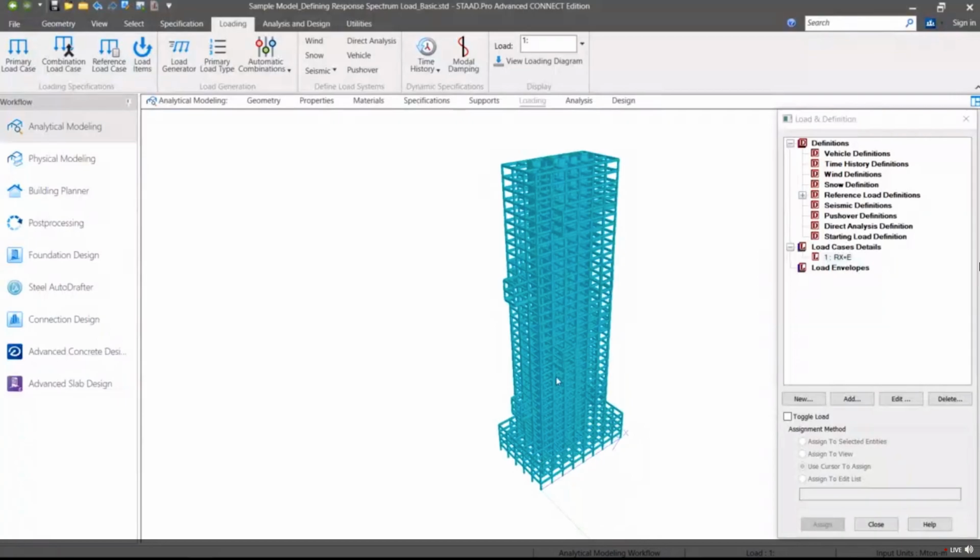Finally, we need to combine these load combination cases with gravity load. Now, there is one very important aspect which we need to consider, the redundancy factor. As the seismic design category of this structure is D, we need to assess the torsional irregularity for this model and accordingly determine the redundancy factor.